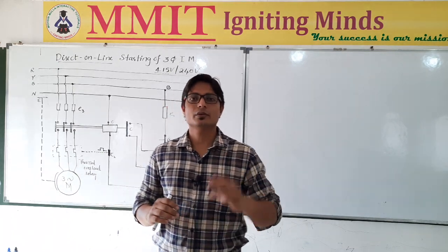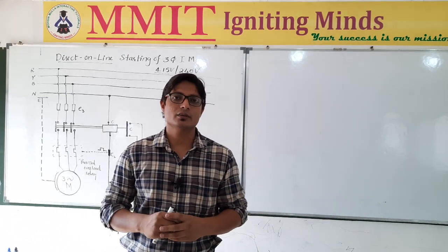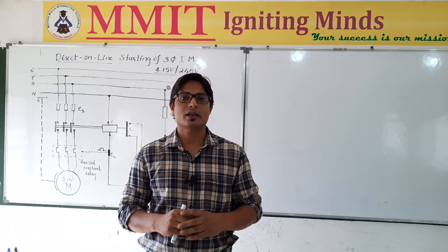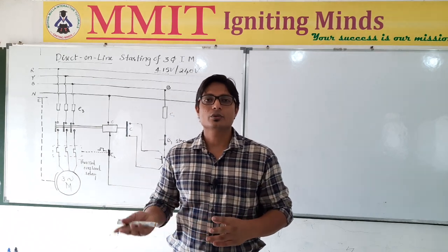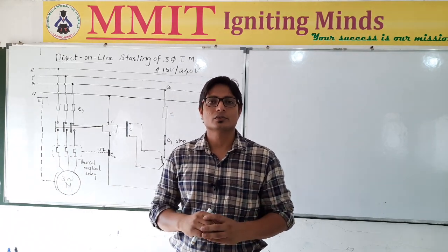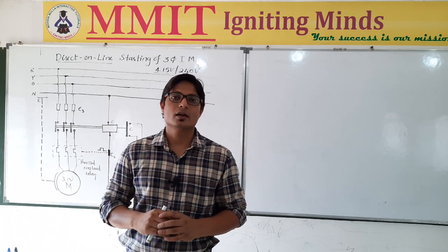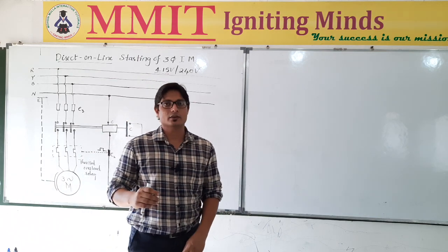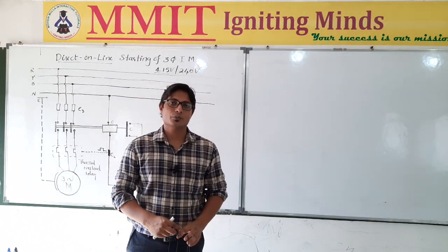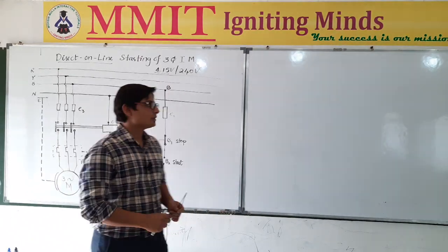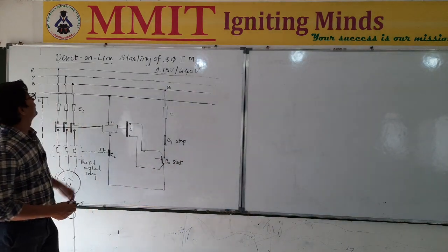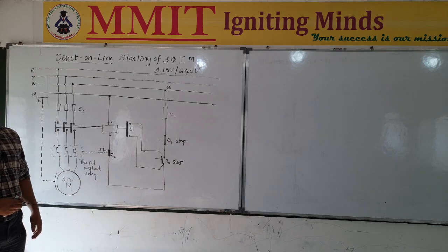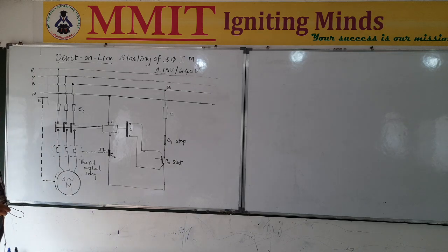Now this can be achieved just by using a simple triple pole switch, but to incorporate motor protection against overload, we need to consider some protection part also. Therefore here we are going to consider an overload thermal relay along with the electromagnetic contactor for the control as well as protection of the three-phase induction motor. So here is the wiring diagram of direct online starting of three-phase induction motor. Let me walk you through all the connections of this diagram.